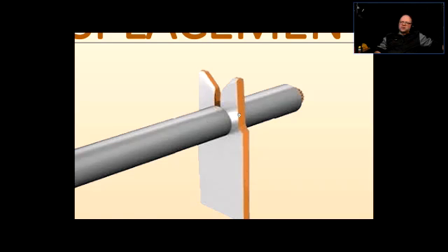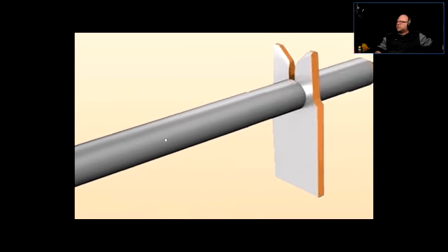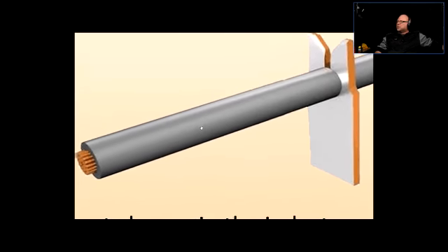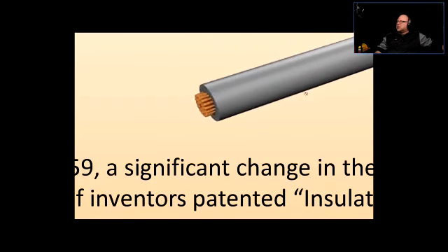Or insulation displacement termination. One thing on that picture I'm going to point out, and I was going to replace it with something else, but I decided to leave it on just so I can point out some of the wrong ways of doing things. I got this picture off the internet and there's a reference there in the posted lecture notes. Over here, you could see this is not a solid conductor, it's a stranded conductor. It's a stranded wire. This is a mistake. That's not a good thing. Right? And again, I didn't replace that because it gives me a chance to point this out.